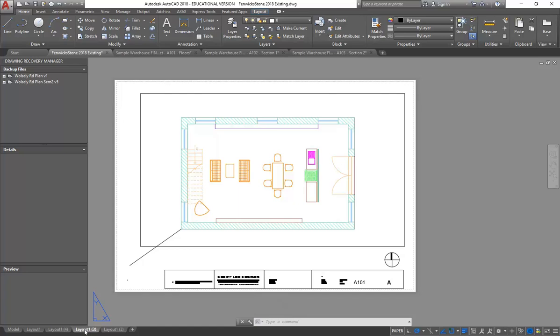So it's a really important thing that you line those drawings up where possible, and drawing in things like lines to set out those locations usually is the easiest way. So now that I've done that, I can delete this line. Then the last thing I was going to show you, we're getting low on time, is how you can set up different layers in the different viewports. So I'll just get you started with that.